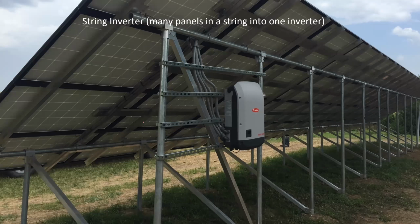Okay, let's talk about some different systems a little bit. There are essentially two types of systems. There are ground-mounted systems and there are roof-mounted systems. Ground-mounted systems tend to be put on some kind of racking structure. And most of the time, ground-mounted systems tend to have large single inverters. In this case, it's called a string inverter because we have a string of solar panels. The string goes all the way down, comes back, and then goes into the inverter. And then there's a second string on the bottom. So this is one large solar array with one large inverter, a string inverter.